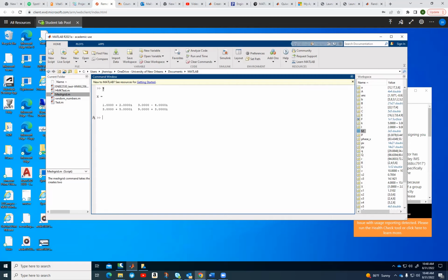I'm going to call one P and one Q. I'm going to use cart2pol for the real part of x and the imaginary part of x, and I'm going to assign the results to both P and Q because I'm going to have an angle and an amplitude, right?